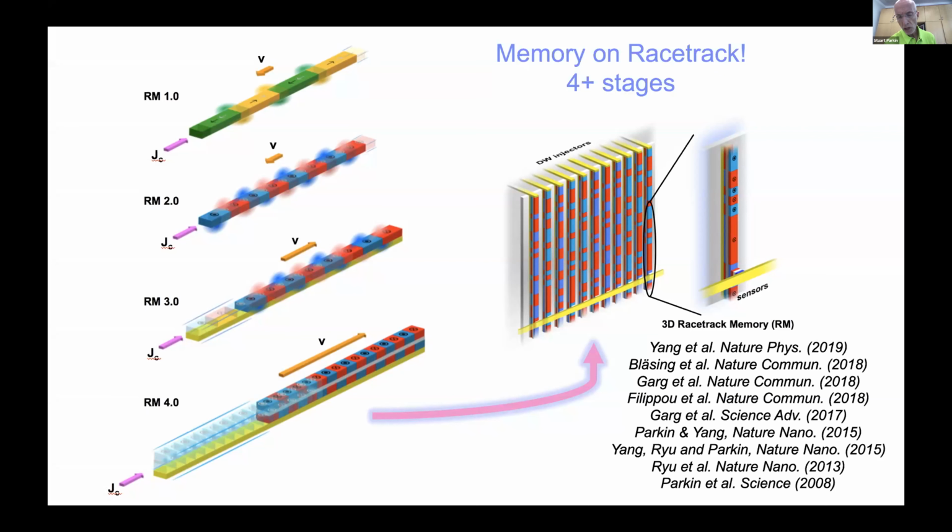Then we could switch to not in-plane magnetized, but in racetrack 2.0, perpendicularly magnetized domain walls, in which now the domain wall size is a balance between exchange and the anisotropy, the perpendicular magnetic anisotropy. This shrinks the domain walls enormously, from a few tens or hundreds of nanometers down to a few nanometers in width. So this is more interesting technologically, and these domain walls are useful technologically.